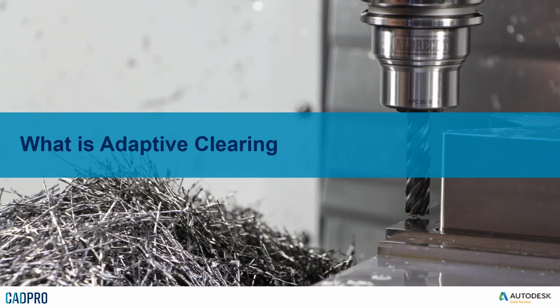All right, so adaptive clearing is one of the core features of HSM, and it's a constant engagement. It never over-engages the tool in the stock when you're roughing and removing material. So the result is usually you can get higher material removal rates in harder materials, with better tool life than you would have historically with traditional roughing techniques.